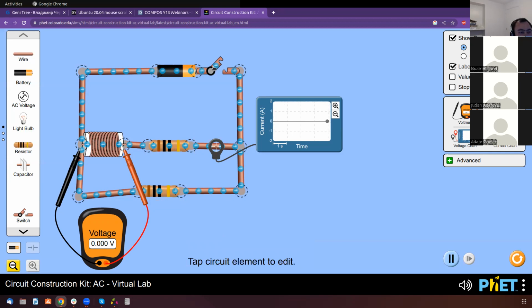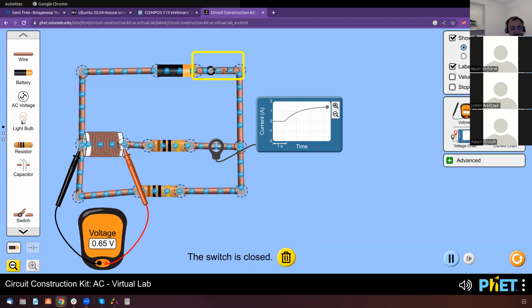So close the switch. And you see that the current grows slower because the inductance is bigger and the resistance is bigger. And now it starts dropping. Once again, closing it, gradual increase in current, and then constant current. And it drops.